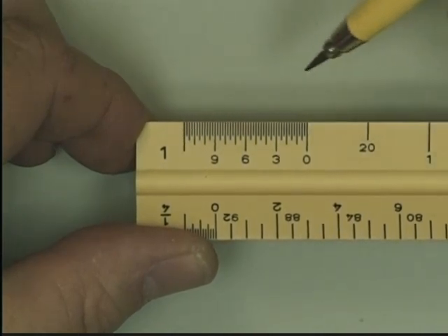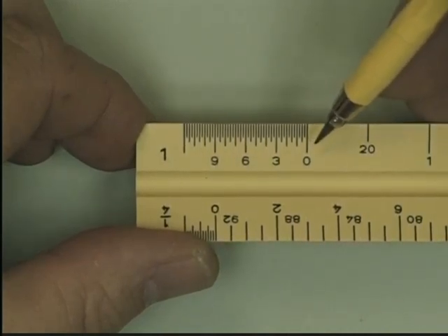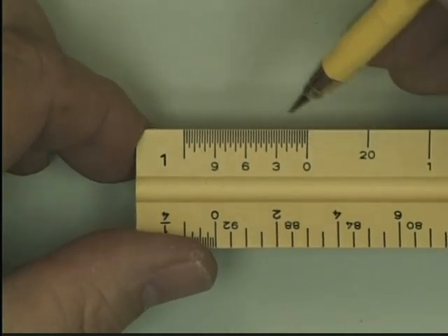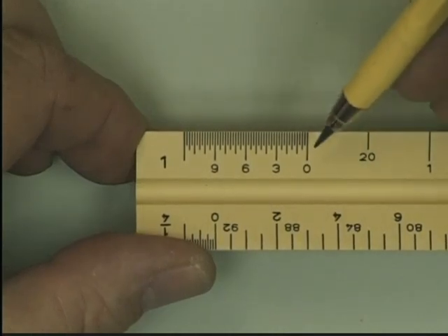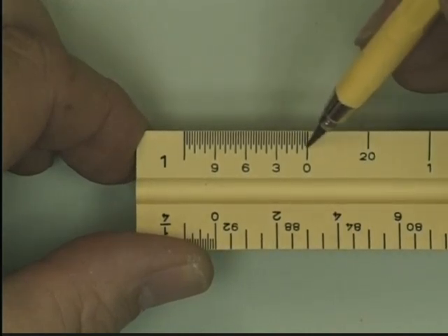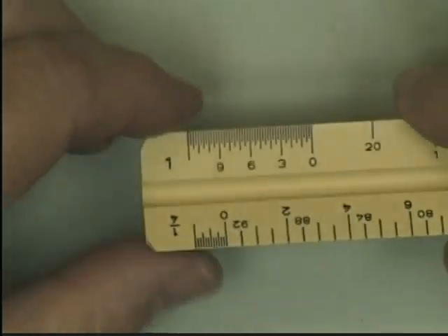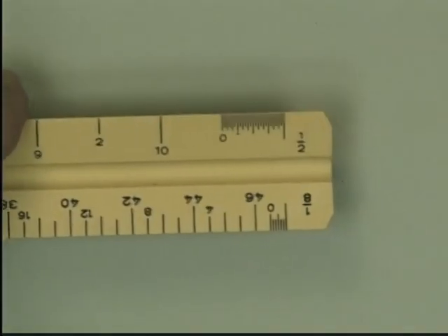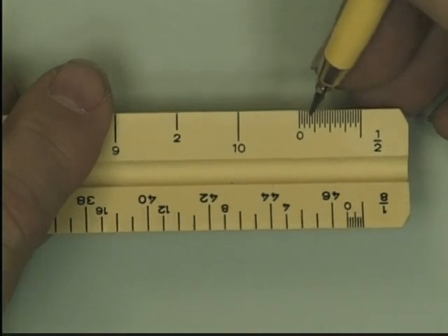Why would they divide a scale into 12 parts instead of 16 parts? Well, architects in the United States work in feet and inches, and each foot is divided into 12 inches. So if you wanted to make an architectural plan, a drawing of a house, where you had 1 inch representing 1 foot, you would have to have 12 parts. Now, on this architect scale, if I go to the other end, you will see a half scale architect scale. This is 1/2 inch divided again, though, into 12 equal parts.